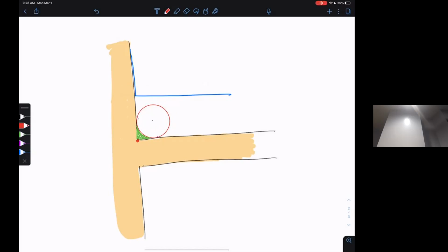Then we're going to make a construction line from that circle to this corner. Now I have that dotted line, which is a construction line. As long as I make my next circle so that its center is on here and its edge is on that point, we get the geometry that we exactly want. Not what I'm drawing, but you can imagine. So now this point has to be on that line. The edge of our circle has to be at the corner, and we're locked in place.